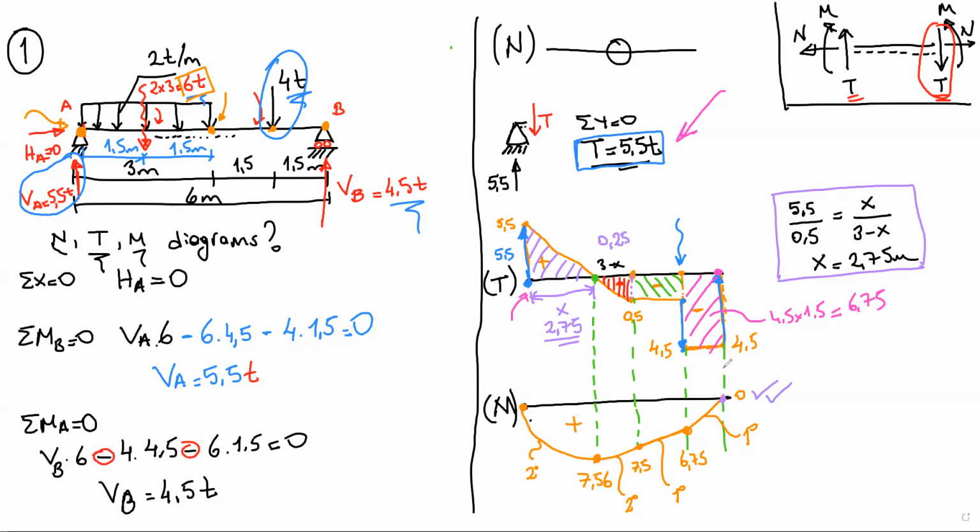This is a self-check for you. Okay, you did all these calculations and you drew this moment diagram. If, for example, at the end, you get a moment like this, here, a moment, somehow, that means you did something wrong somewhere else.